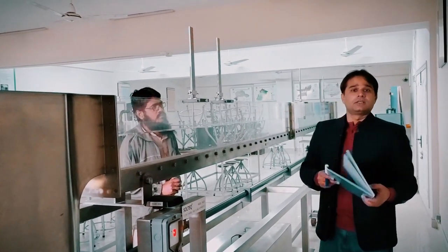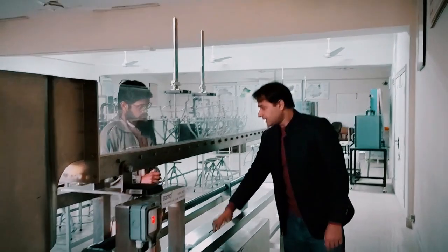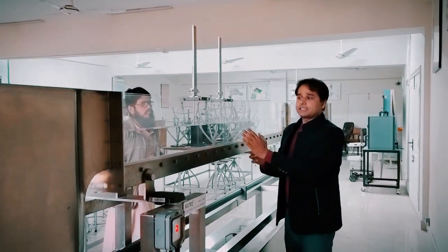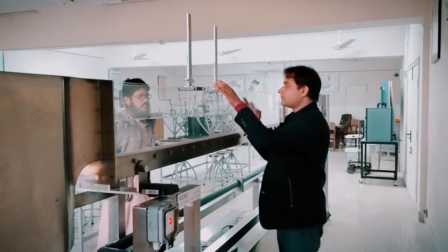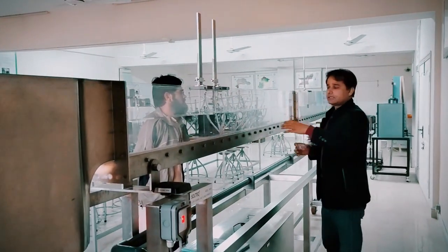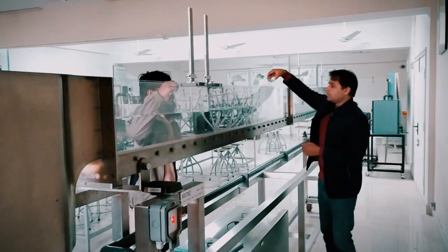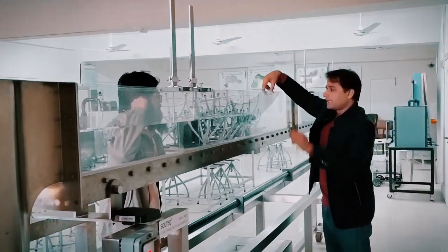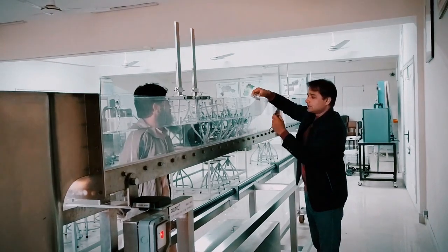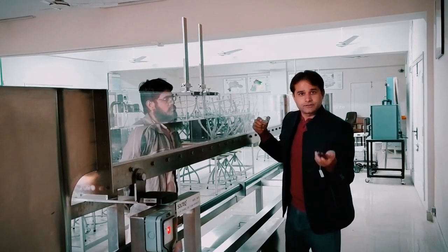Our next step is to measure the flow velocity. For that we have to insert a floating body at point 1, and we have to wait until it reaches point 2. The machine will help us to control the body. It will stop the body, so it will not go beyond this point. I will insert this body in the middle of the channel, and when it reaches point 1, we have to turn on the stopwatch. After reaching point 2, we have to stop it.